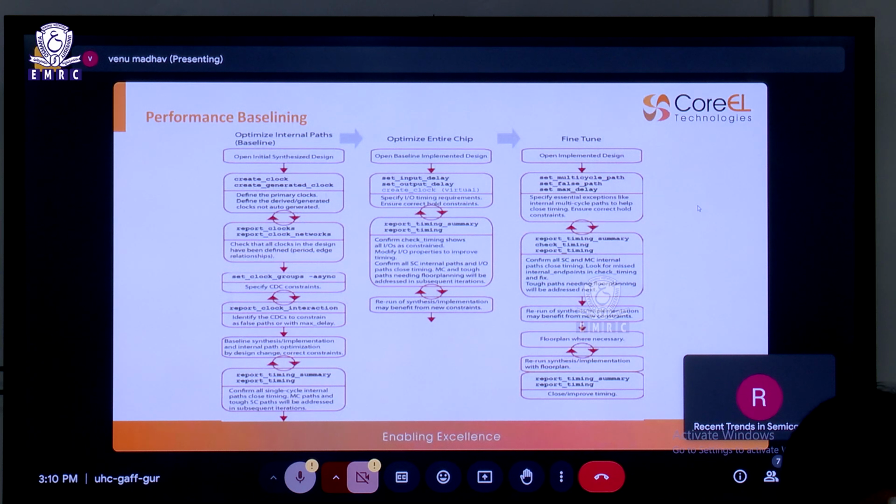Let's say there is a very long combinational path. A very big combinational path exists. Inside a combinational path, it is hard for us to correct the timing. We can calculate the timing obviously, but it is hard to correct the timing, because we only have delays there.